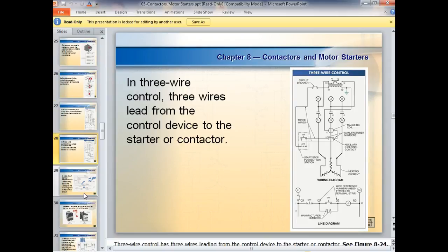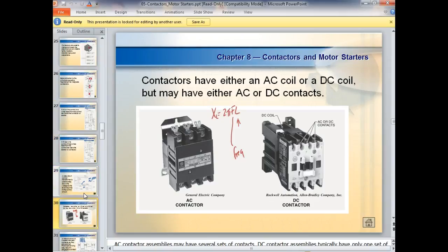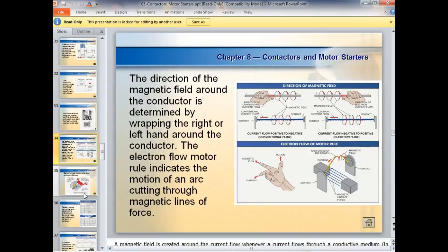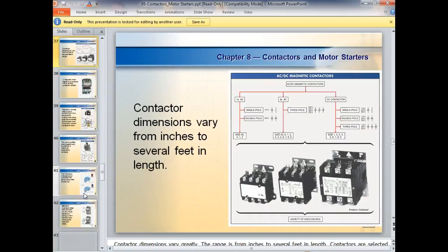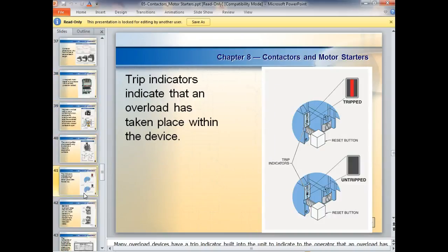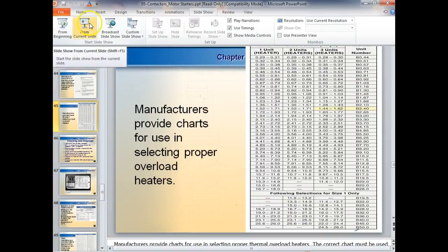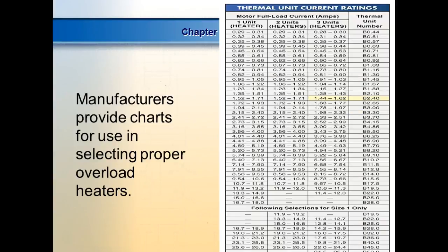The first thing we're going to do is take the 1.6 amps and multiply it by what? 0.9. What does that give us? Okay, so this is the manufacturer's overload chart. This is not necessarily the one that you'll have, but your manufacturer provides this for us. So right off the bat, we multiply by 0.9, what do we get?